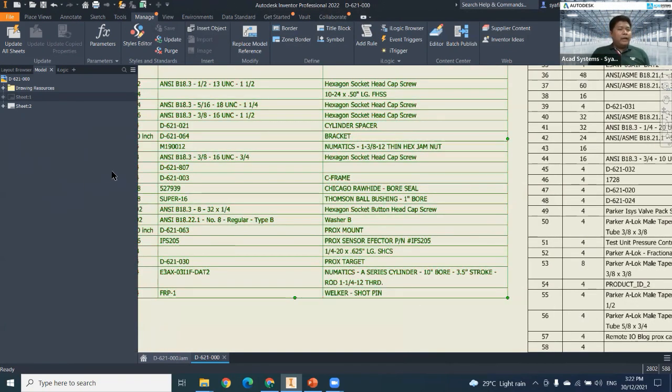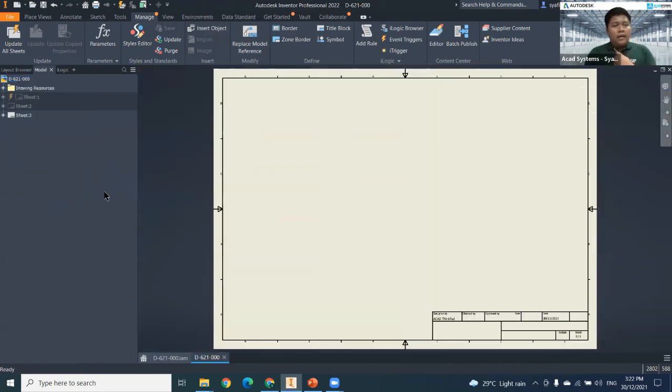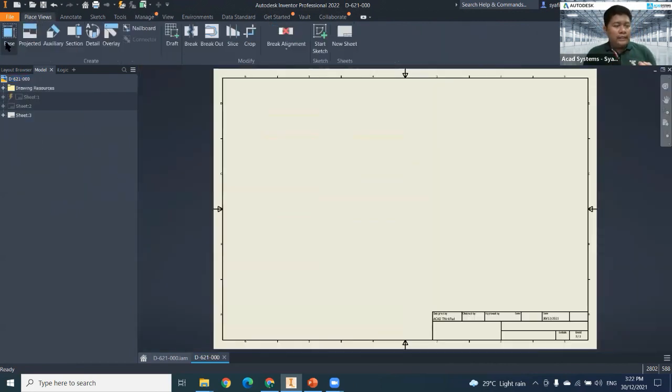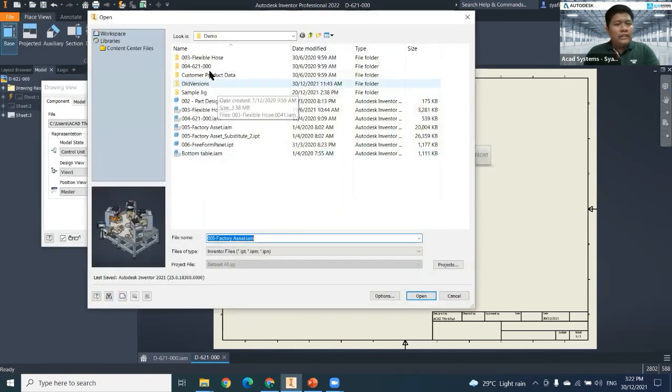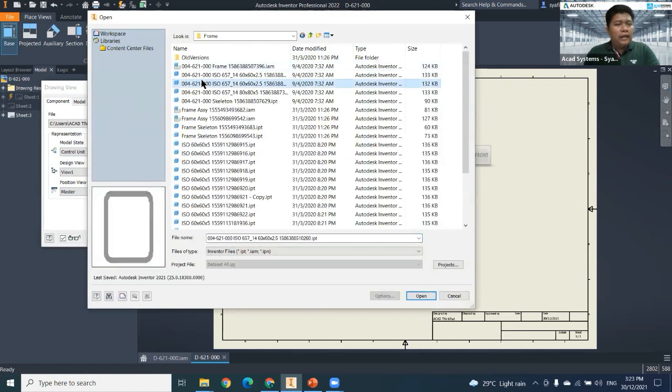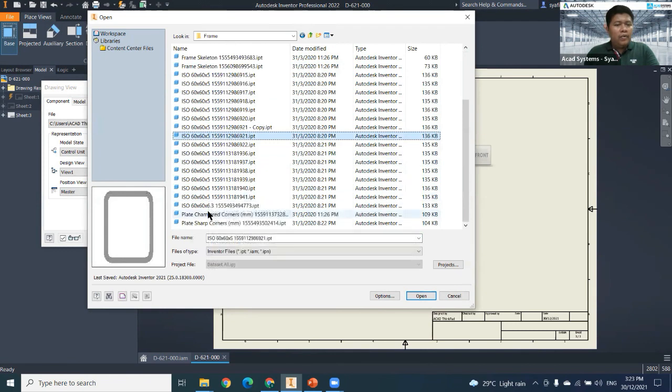Okay, and the last one. I want to do some optimization for selecting items. This will be the normal method when you try to do part insertion. You want to place a part, manually insert, so you need to do something like this. You just need to go to one item and then choose 1, 2, 3, one by one.